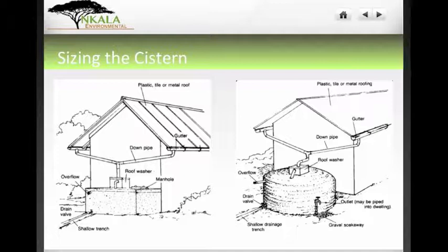This is a ferrocement tank, and essentially you can design it to have various types of shapes because it's essentially plastered. You're plastering the ferrocement onto a wire mesh, and so it gives you more flexibility of being able to design it. So if you want an amenity, you want a nice looking tank, and you want it to add value to your house, you perhaps could use ferrocement, which is maybe less expensive than reinforced concrete, but it can still be expensive depending on what you're looking at. But we basically have the same elements here.